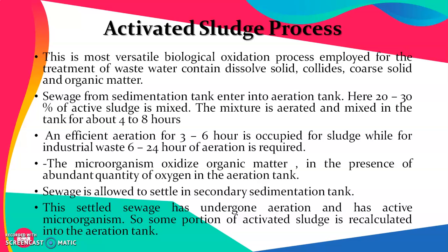In these 4 to 8 hours, a very high amount of active microorganisms, which are very fast in degrading or consuming the organic waste present in the wastewater, are the major part of the sludge which has been mixed into the wastewater to be treated in the aeration tank.